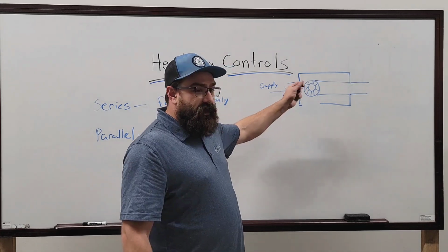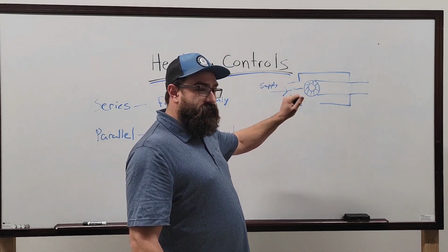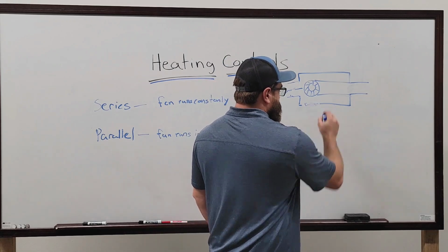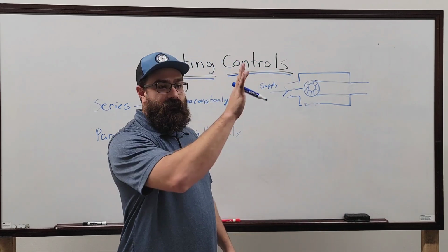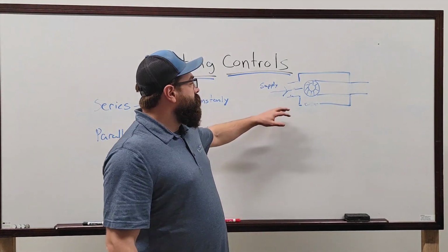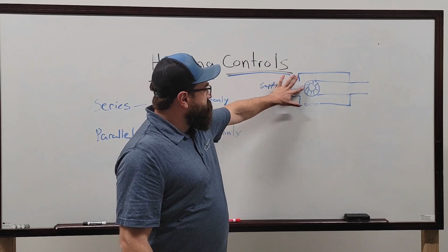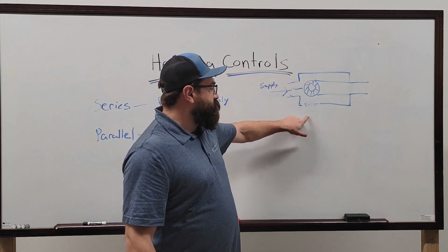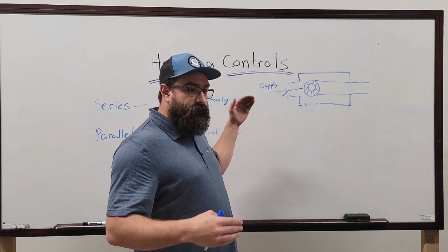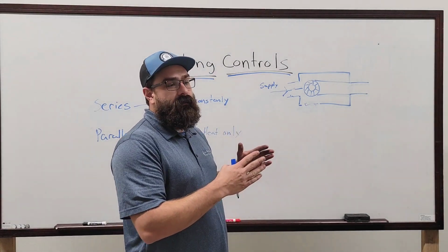They have a little potentiometer in the fan that you can turn the speed up and down to where this becomes neutral. It's not positive or negative, it'll flutter a piece of paper. It's no pressure and no negative. What then happens is this damper modulates, it will start to draw air in from the return, mixing plenum and supply.